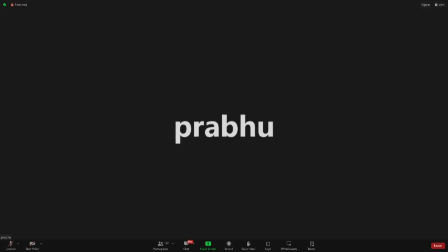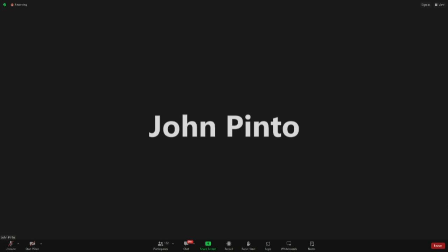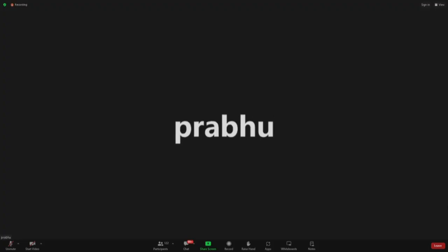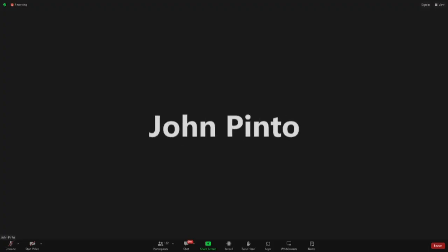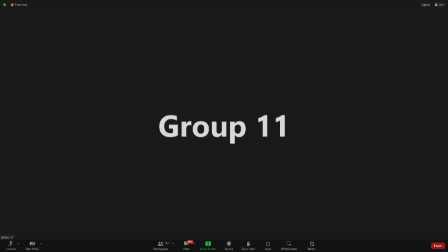Okay, when I'm typing paraFoam, it's not opening. That means there's some error occurring there. Yeah, so please write in the chat, and maybe one of our TAs will give you a meeting link, and you can share your screen and show your problem to them. It may be some small problem. We'll rectify that. Okay. Hello? Yeah, sir, I am getting a fatal error in which it is saying cannot find patchField entry for inlet.